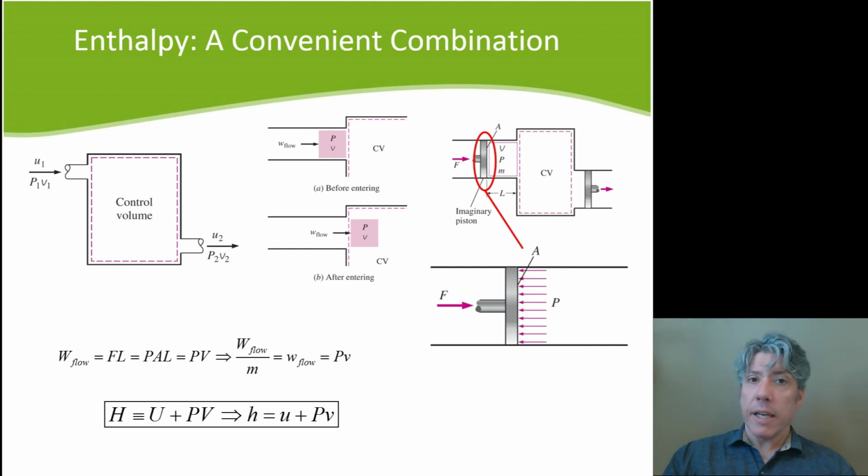You can calculate enthalpy from a table where you've got the specific volume and the internal energy of, say, air, and you've got its pressure and specific volume. You can calculate the enthalpy of the air. That doesn't mean that flow energy actually exists, because it's not flowing. The only time the PV energy exists, and you can call it energy, is when it's actually flowing and therefore doing work.